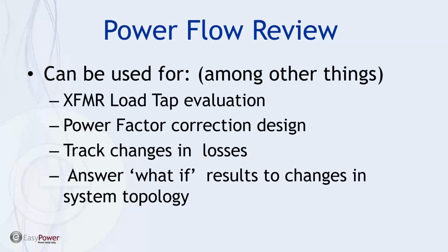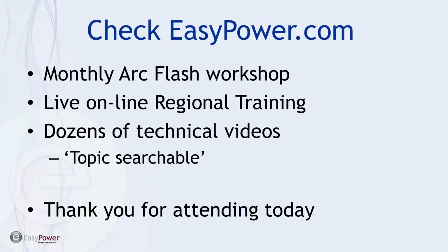So among other things, PowerFlow can be used for transformer load tap sizing, power factor correction, tracking changes in losses or impact on capacity if I'm going to be able to de-energize or move equipment around. And above all, it gives us the ability in very short order to go through what-if scenarios to answer some initial questions or give us some direction on how to deal with changes in the topology. I think that's what we wanted to cover for today.